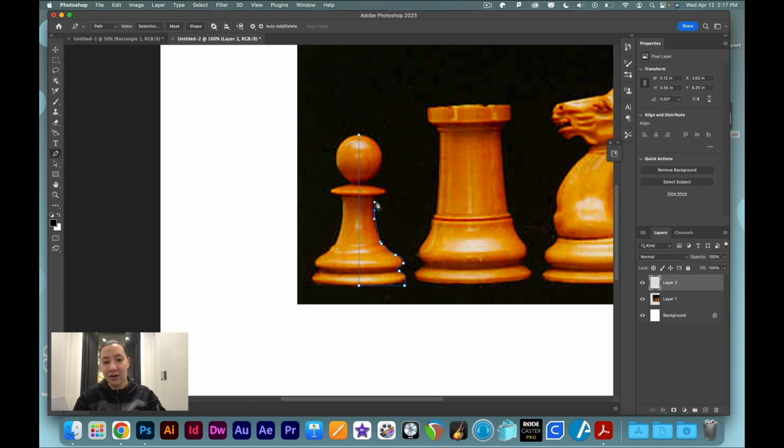to about here. And when I get to this ledge, this is not going to print perfectly the way it is if I was to just follow this line, because there is no structure supporting this overhanging sort of decoration here. So I'm going to make a straight line that is a little bit diagonal from, let's do one more point up here. From this point all the way to the outside edge. So even though it's not following the pattern, this will make things easier to print in the future. So then I'm going to just make another curve.